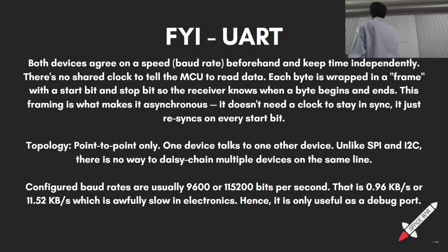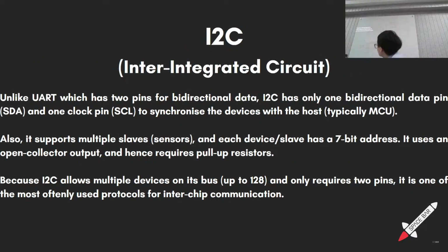These two lines are called a bus, and we can wire up to I believe 128 devices. 0 is reserved, I think. Because 7 bits, I'll show you the protocol. Something is reserved, I just remember there's a minus 1. Anyway, you're never going to put 127 devices on one bus.